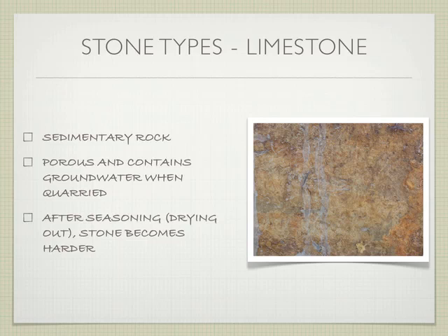This one. Perfect. So you can see on this one there's a bunch of little cavities and holes in it that can absorb water, which also makes it a challenging building material. It's something you have to pay attention to in relation to limestone. After what's called seasoning, the stone does become a little bit stronger once you remove the water.